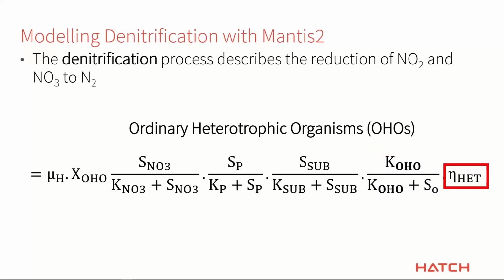And then this last term here is the anoxic reduction factor. So this is actually related back to this thing. I probably should put it at the other end of the equation here. Basically, this is the same growth rate that you would use for aerobic growth of heterotrophs. So that's just doing regular BOD removal. But then we multiply it by this term here, amongst everything else. And this is a number like 0.4 or 0.5 or 0.3, something like that. There's different values for different circumstances.